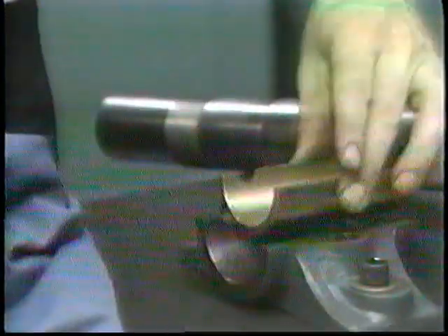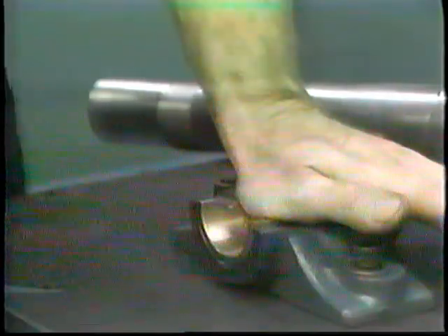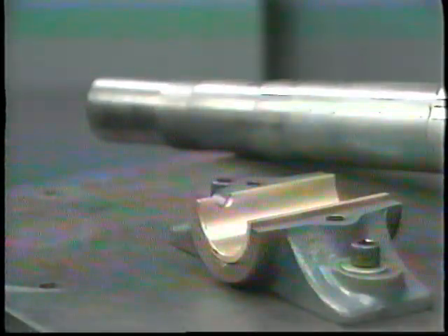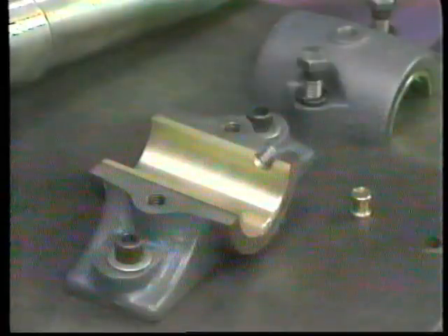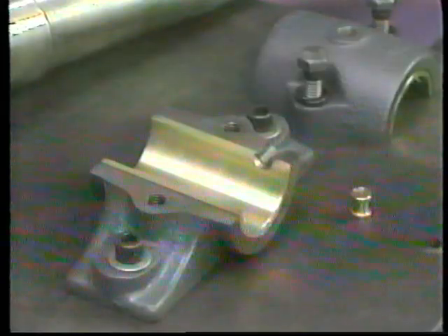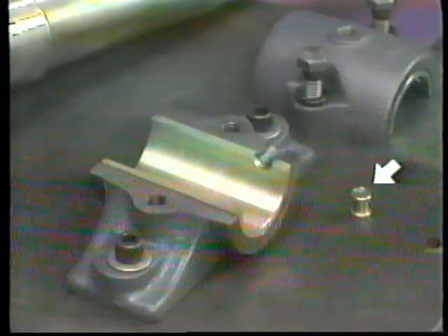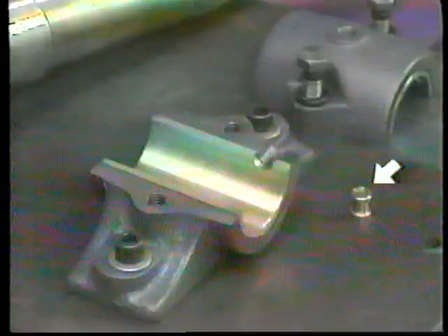Initially, mark the housing in such a way that will allow you to reassemble correctly. Check the shaft or journal to ensure that it is not tapered, oval, scored, or rough. Always inspect and clean the back of the bearing and the mating surface in the housing carefully. Dirt under the bearing may reduce clearances and prevent adequate heat transfer. Usually, a dowel, screw, spool, or lug are used to keep the bearing in place and prevent rotation.